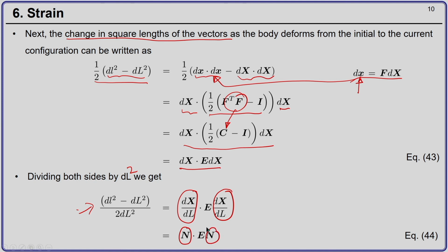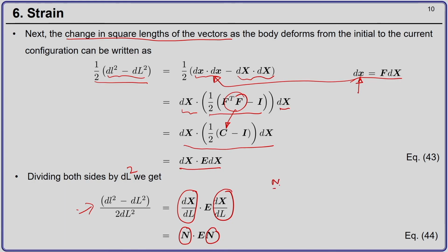Now, if you remember, in one of the previous examples when we were linearizing different strain measures, the third example was the Green-Lagrange strain, the 1D version. So, now we can derive that here. If I take N as E1, N is a unit vector along the x1 direction, which in vector notation is 1 0 0. And if I substitute it here, what do I get?